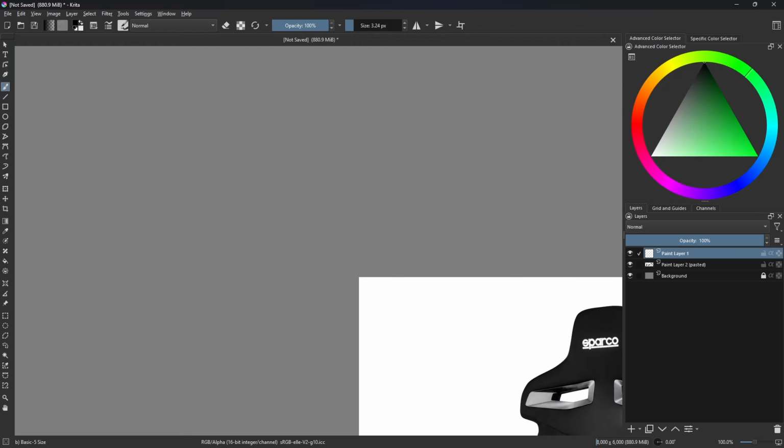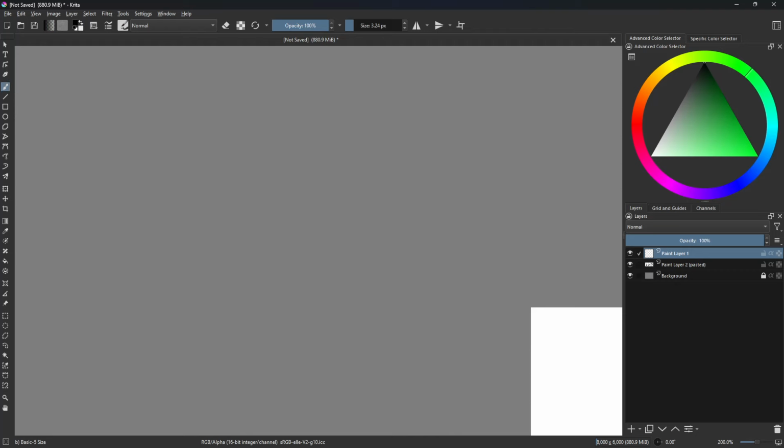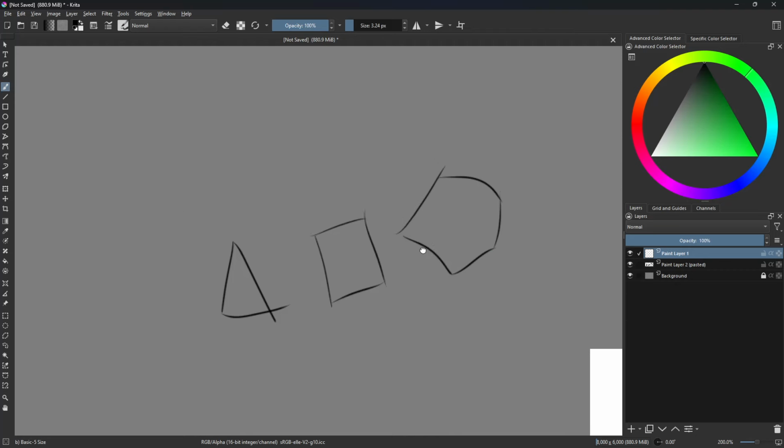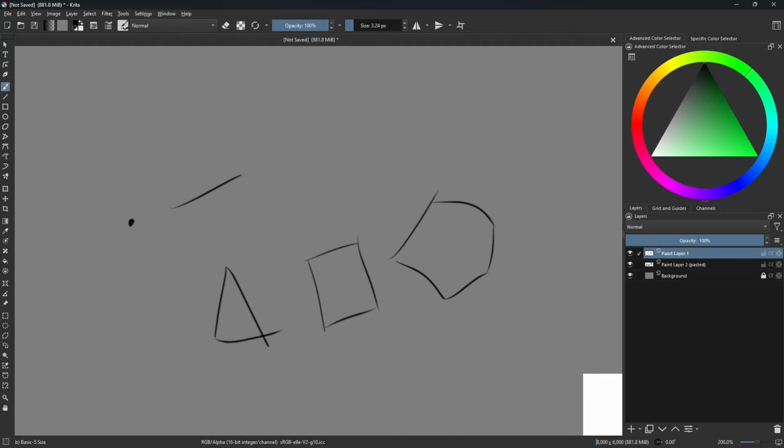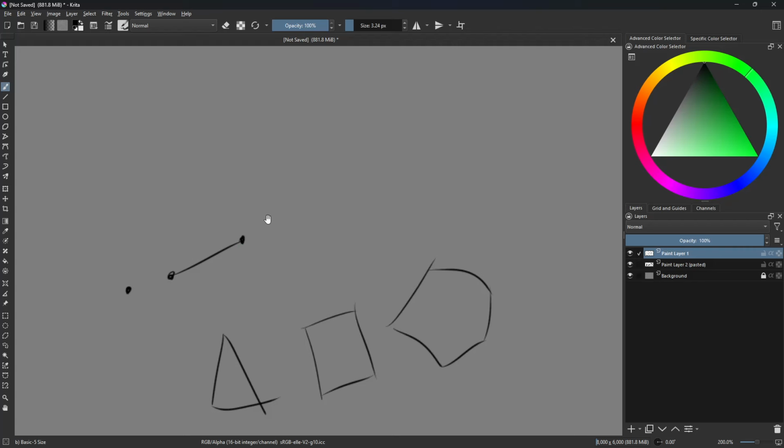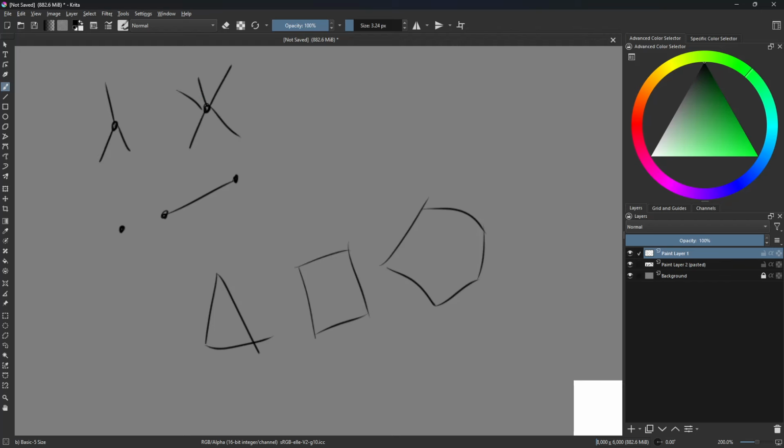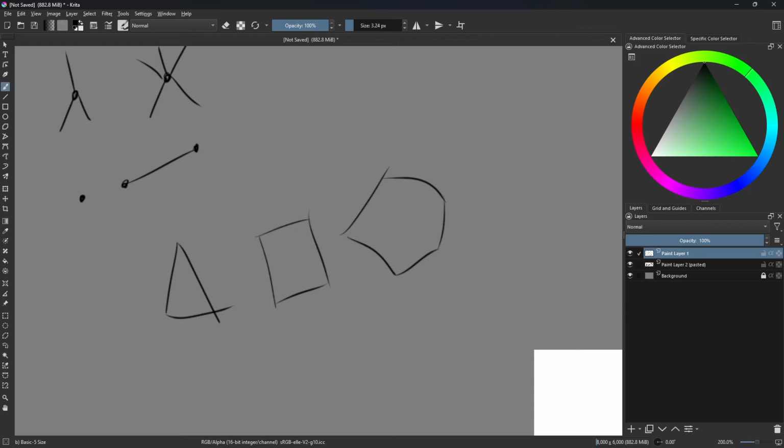So first, when you're working in Blender, the main thing is that you have only so many faces you can use. There's triangles, there's quads, and then of course your n-gons, right? But your models are made of vertices, edges, and then you have vertices that are n-poles with 3 edges coming out of it. You have vertices that are e-poles with 5 or more edges coming out, up to an infinite amount. All of your 3D models will have this, period. Like that's what's going to happen in Blender anyways.